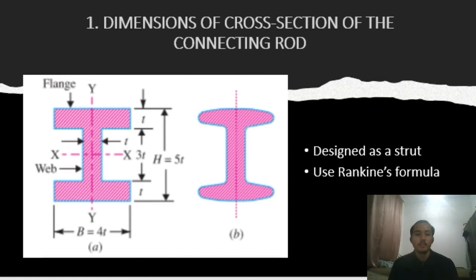In order to have the con rod equally strong in buckling about both axes, the buckling load must be equal. If I section at X axis is greater than at Y axis, the buckling will occur at Y axis. And if the I section at Y axis is greater, then the buckling will occur at X axis.